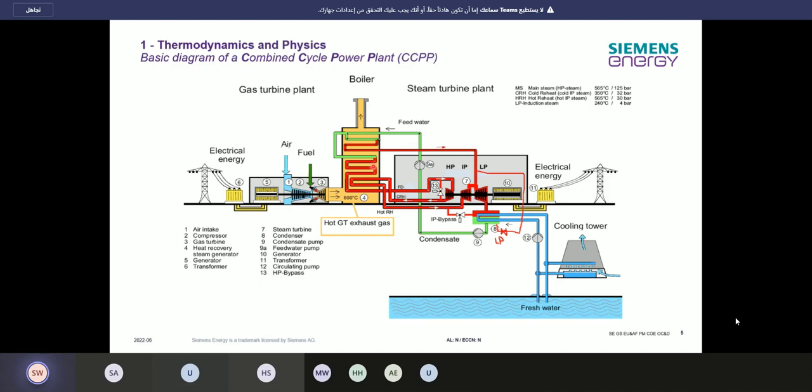And that's what we have inside the evaporator. So the evaporator is designed for it. There, the evaporation process can take place. It should not take place in the economizer or the preheater. It should take place in the evaporator. So we need to make sure the temperature we're getting into the evaporator, or out of the economizer, needs to be below the boiling point. And then in the evaporator, the steam will be produced.